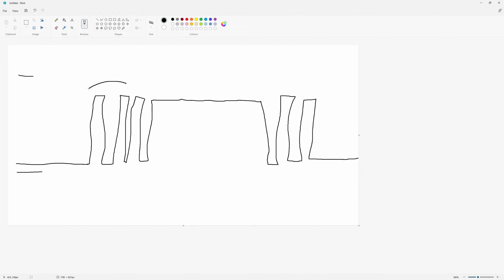Now the problem is these jumps on the rising edge and falling edge. These jumps will cause multiple triggers to be detected on the chip. Now with FPGAs, this is more of a problem than with microcontrollers, because with microcontrollers, you have your processing delay. With FPGAs, everything is in real time. It's basically real-time actual logic.